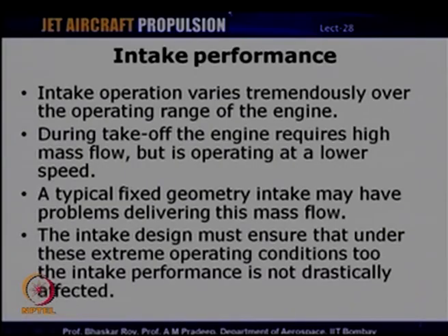Because intake operation varies tremendously over the operating range, for example, during takeoff the engine requires a very high mass flow, but it is operating at a low speed. And so, a fixed geometry intake is likely to have issues delivering this mass flow during takeoff, and it is the duty of the intake to supply the required mass flow without affecting the engine performance.